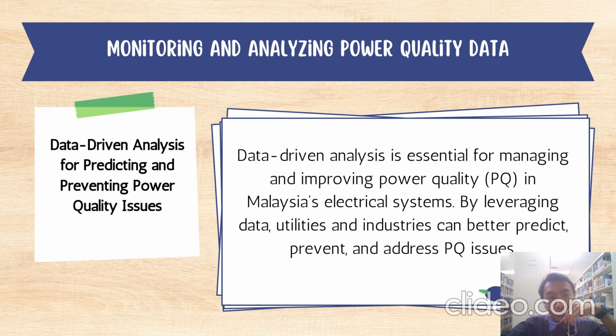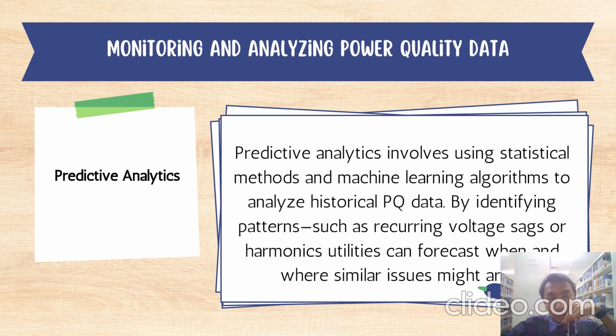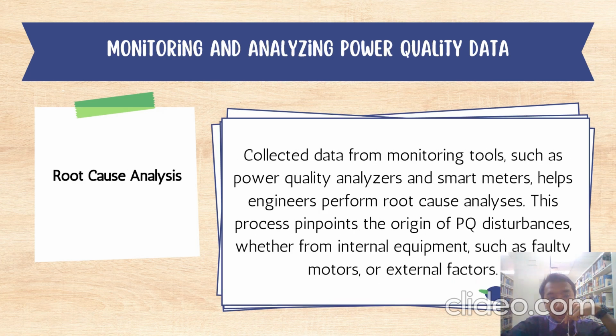Data-driven analysis for predicting and preventing power quality issues. Data-driven analysis is essential for managing and improving power quality in Malaysia's electrical system by leveraging data. Utilities and industry can better predict issues. Last but not least, root cause analysis. Collected data from monitoring tools such as power quality analyzers and smart meters help engineers perform root cause analysis.